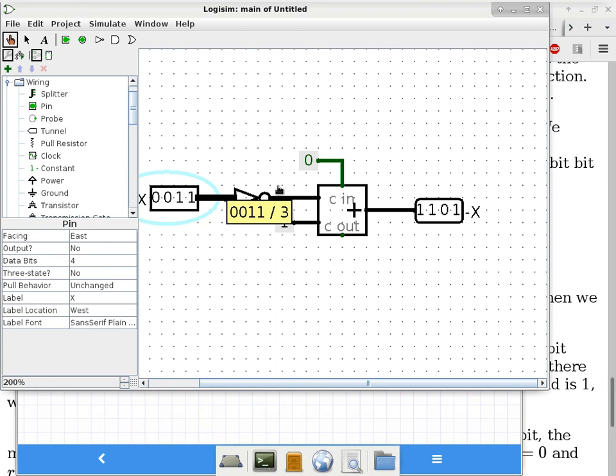In other words, when I click this wire, it will show 1, 1, 0, 0 as the bit pattern because it's just a bitwise not. But what is the value it is representing using the signed interpretation? -4, because we have to go from 0 and then we click 4 times counterclockwise on the number wheel. So let's click, making sure that is the case. It's all good. And then -4 plus 1 is -3. So that's why it works.